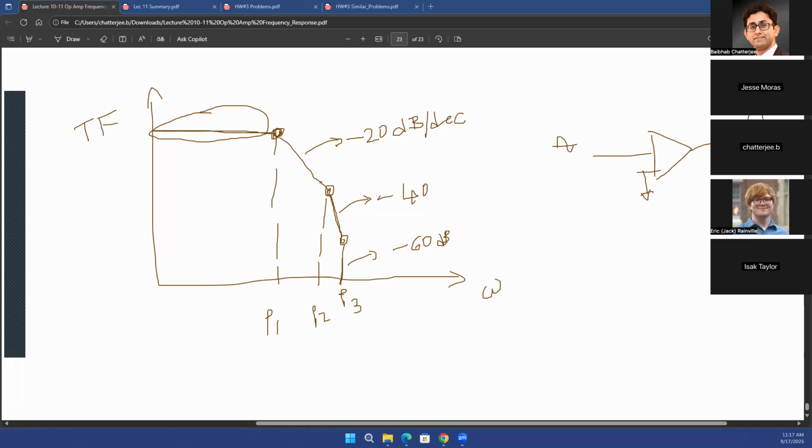However, real systems may not always just have a sine wave, right? You know how an ECG looks. Many of you already know how the ECG of a person looks, right? It might have some peak, maybe a little bit of fluctuation here, again a P wave, QRS-T, and then like this. So this is not a sine wave in real life. If you want to amplify an ECG signal, which is millivolt level, a very small signal, you want your output to look exactly the same as the input, just an amplified version.